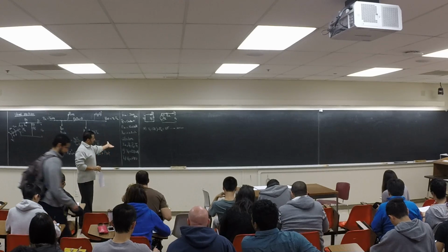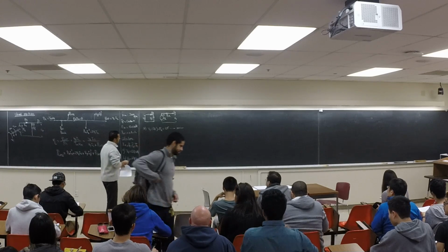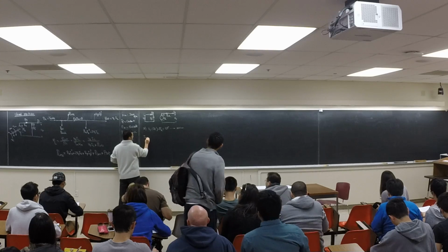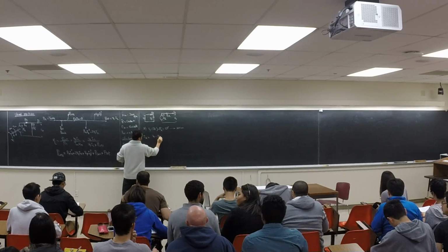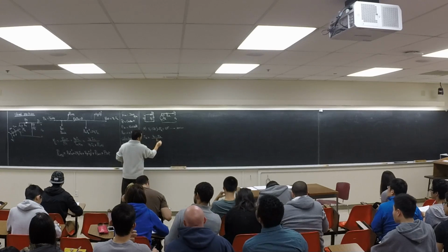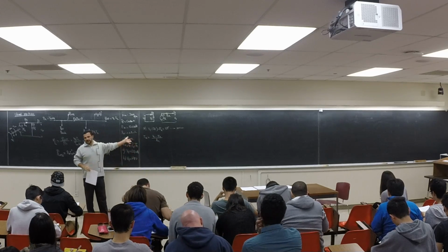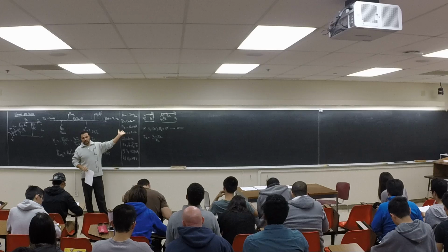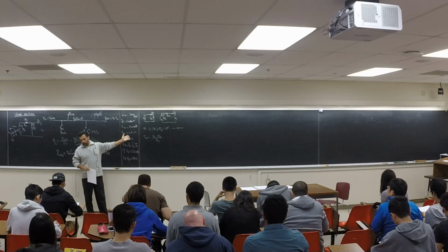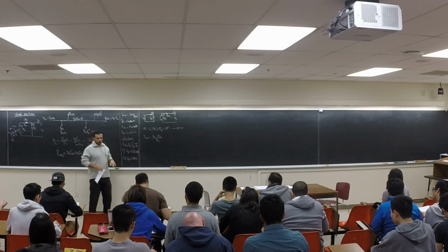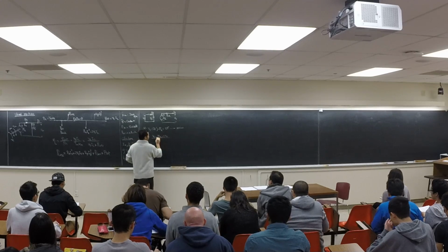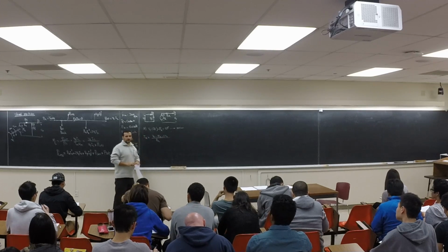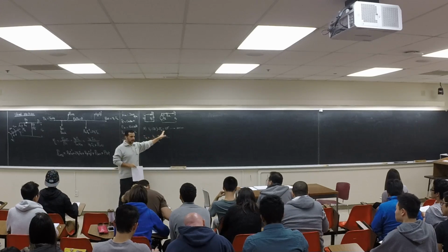So how much is the IA now? Very simple. IA is equal to VT minus EA over RA, right? It doesn't say anything about the brush voltage. I'm not putting any number over there. But if you had the brush voltages, for example, if it's 1 volt per brush, I'll put minus 2 VB, so 2 volt here, I'll add that one.